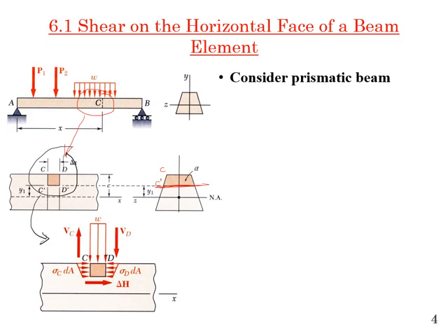So at C we have a shear force, following the sign convention. If you remember, if you're taking a section from right to left, shear force upward is taken as positive. If taking from left to right, downward will be positive. We take shear force downward. And this is the normal stress distribution on this area.